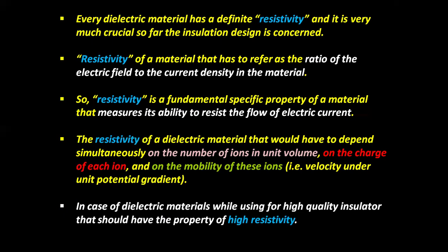The resistivity of a dielectric material depends simultaneously on the number of ions in unit volume, on the charge of each ion, and on the mobility of these ions, that is, velocity under unit potential gradient.